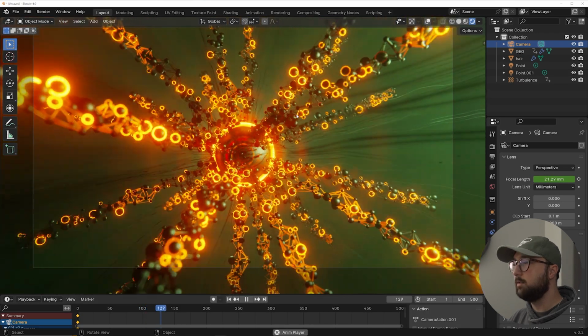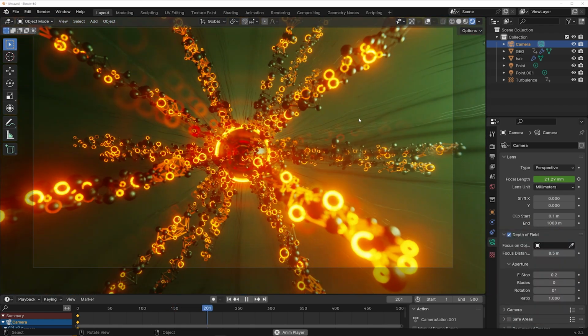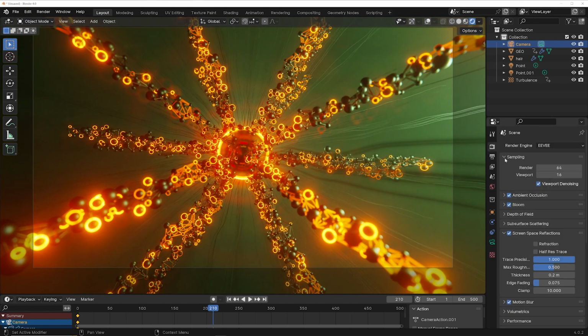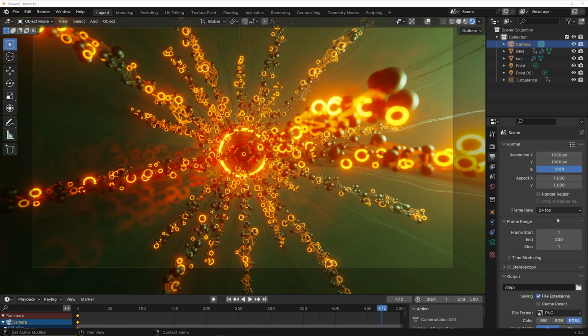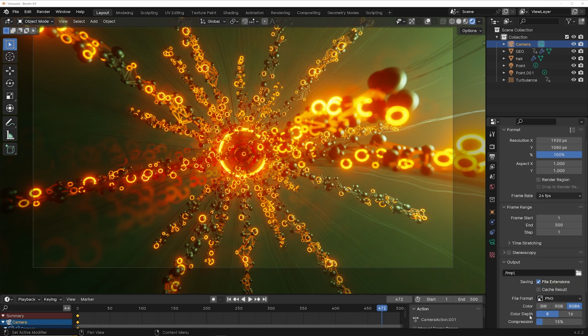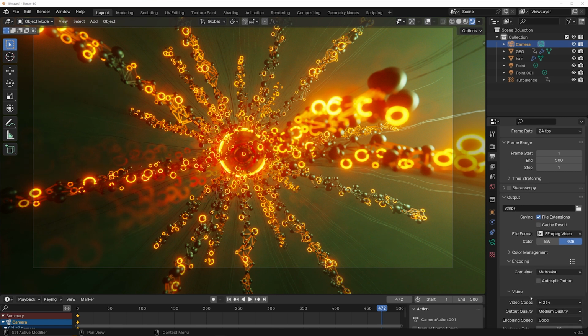And this animation is finished. We are all done. Now let me try to export it and you can be on your way. On the format, the little printer icon, I would keep it at 1920 by 1080. If you want 4K, just type in the exact pixels you want. Then you can use a PNG sequence, but if you just want an MP4, like a finished video for yourself, you'll do FFmpeg video encoding to MP4, and then medium quality to perceptually lossless, render animation. And of course, pick your file location. So there you go.